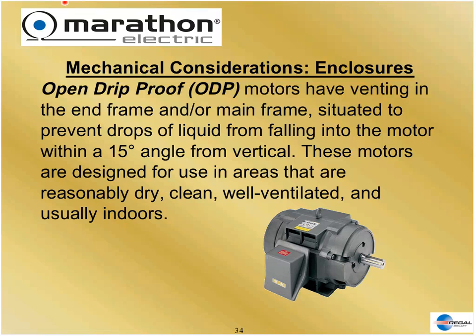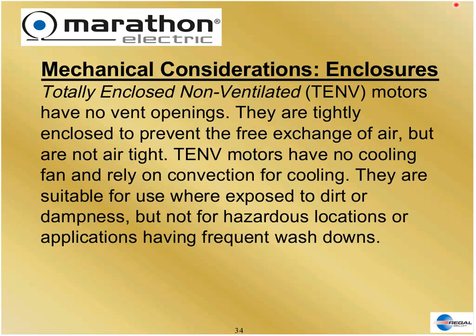There's a fan inside the motor that draws the air in. It draws the air in these openings and blows it out other openings. So the room air goes through the motor and out. That really takes the heat out and is a very efficient way to cool the motor, obviously. However, sometimes the environment that the motor's sitting in is not conducive to being inside the motor. It might be wet, it might be dusty, it might be caustic, it might even be volatile.